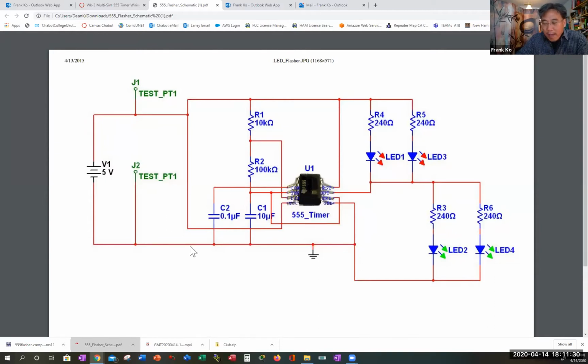Okay. Going back to when we started playing with LEDs. LED stands for what? Light emitting diode. Yes? It is not a light bulb, but it can burn out. And unless we have a resistor connected to an LED, that LED most certainly will likely burn out. So anytime you see an LED in a schematic, start looking for some kind of a resistor.